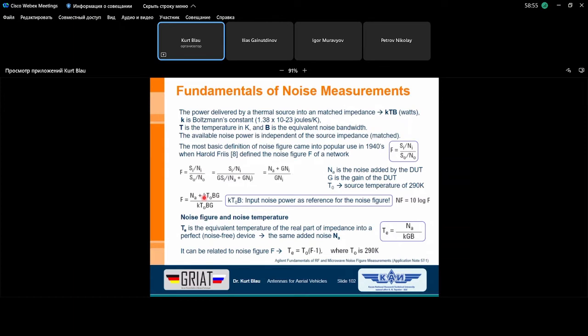Most amplifiers, also broadband amplifiers, have a more or less low pass characteristic, or in a lot of cases a band pass characteristic. This means the so-called DC amplifier has a low pass characteristic, and RF wideband amplifiers also in a lot of cases have a band pass characteristic. This means at lower frequencies there is a high pass character, and at much higher frequencies a low pass character.